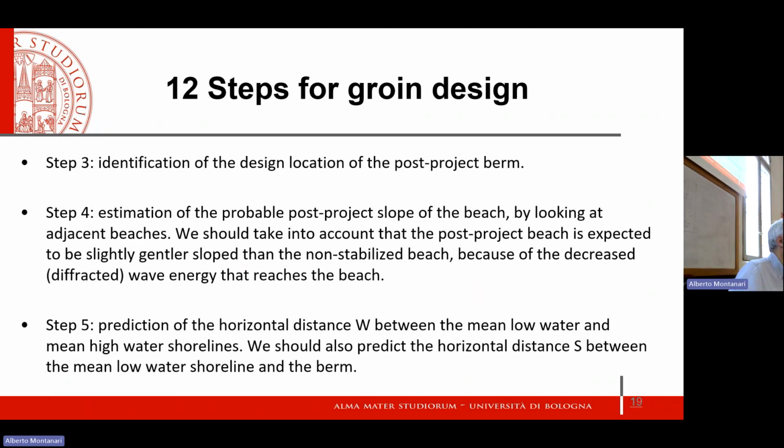Again, this is something that analytically it's difficult to solve. You can apply a numerical model, but my first suggestion would be look around. Look around in a situation that is undisturbed and look at the slope of the beach in that situation. Or look into a similar situation. Sometimes when I say look around, the implication is that you don't look at a great distance from you. But actually, you may get a similar situation even in another continent, provided that you have similar wave regimes. It is possible to find inspiration from locations that are completely elsewhere, provided that you have good reasons for ensuring similarity of the context.